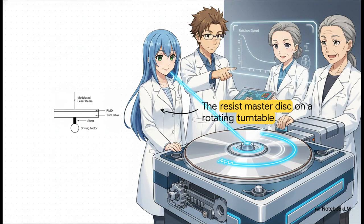Now, during that initial laser exposure step on the turntable, engineers face a really unique physics problem. As the laser moves from the center toward the outer edge, the track radius gets larger, right? So to keep the laser scanning the surface at a totally constant velocity, the driving motor actually has to slowly, continuously reduce its rotational speed. It's a brilliant mechanical dance.